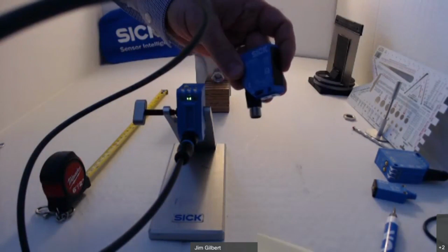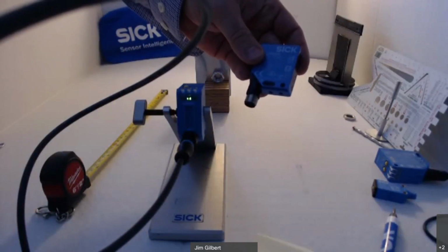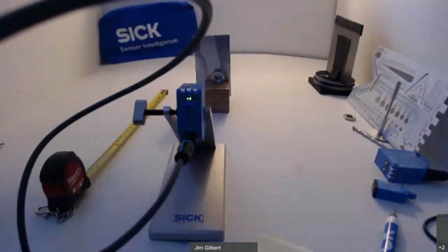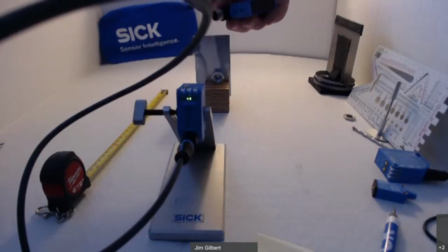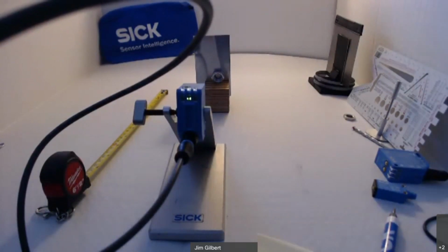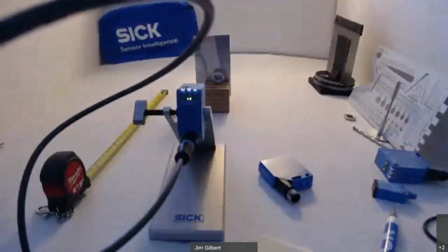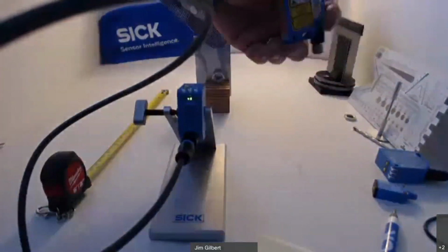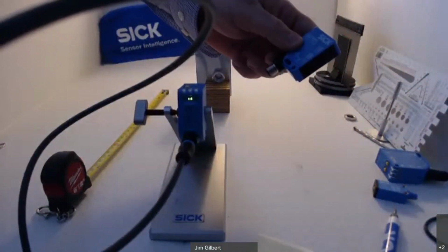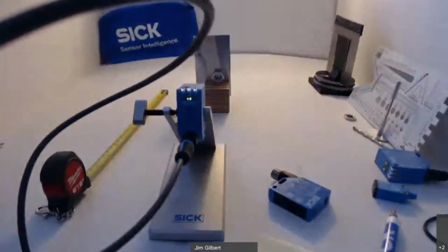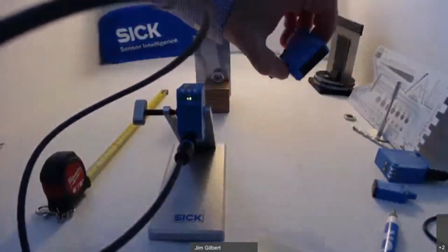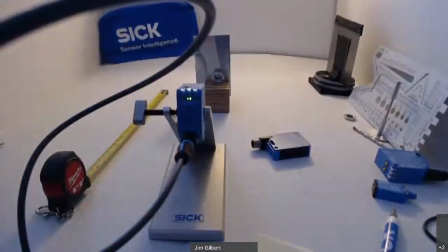Another sensor that would be good at that is the background suppression version. These both can resolve very small differences between the target and the background over relatively short distances, say maybe upwards of 600 millimeters, maybe up to a meter. This particular one is really good. You could do something like resolve the thickness of a business card laying on a table. If you had a more precise application, it would probably lean towards this type of product, similar to the image that we had shown before with that piston ring.